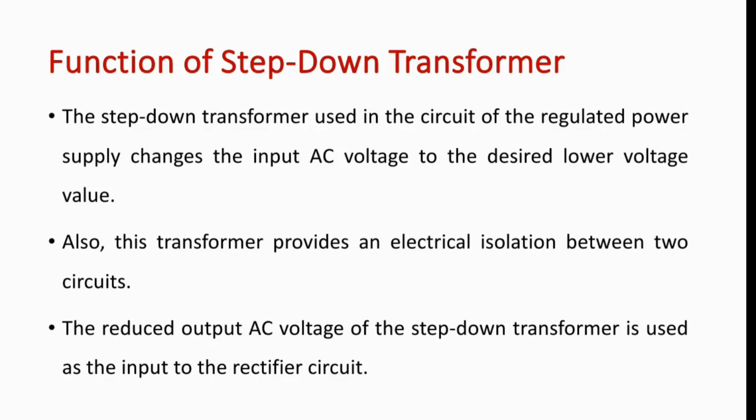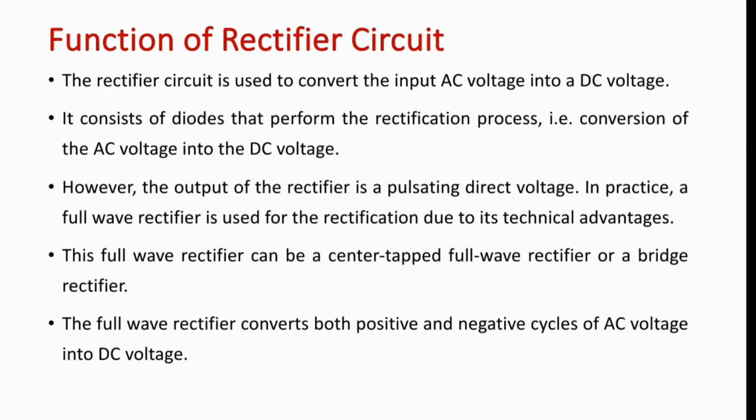So this is the block diagram of a regulated power supply. First, we have the AC voltage input, and finally we have a steady DC output. How are you going to convert the AC voltage input to a fixed DC output voltage? First we have the AC voltage source, then the transformer, after that the rectifier, then the filter circuit, then the regulator, then a voltage divider, and finally the output. So let us see how each step is taken care of.